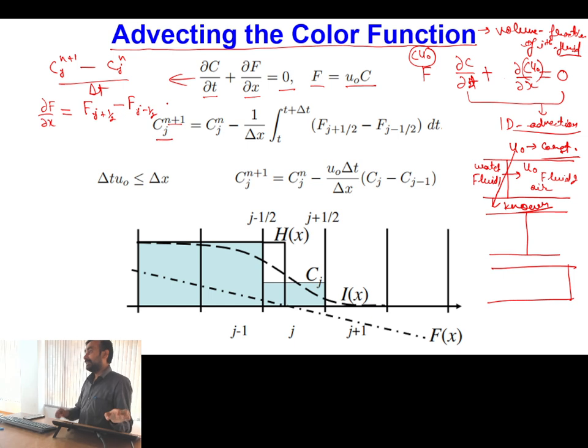Now I am not giving its detailed integration, because if you recall, when I showed you the FVM discretization of the scalar transport equation, in the advection term we had rho u into phi. When we performed the numerical integration of that term, we found rho u phi at point j plus 1 by 2 minus rho u phi at point j minus 1 by 2. All are clear with this idea? So that is coming from that particular lecture. Detailed steps I am not showing over here.